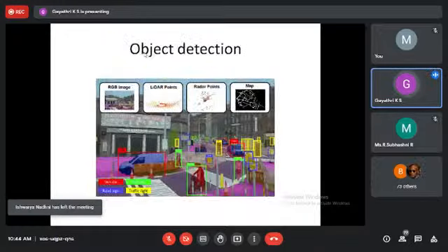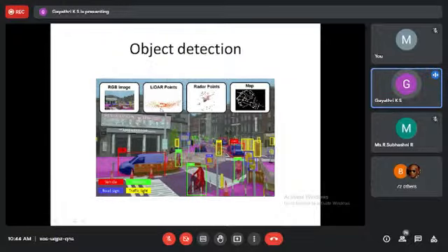So there is a set of algorithms called object detection algorithms in machine learning and deep learning. When you give the inputs of your cameras, your LiDARs, your radar, and the HD map as input to this algorithm, that algorithm will be able to tag. You can see this tagging in the sense of a bounding box. All of you know what a bounding box is. You put a bounding box, and it tells you this is a car. The probability of this being a car is 0.99. The probability that this is a bicycle with a person riding on it is going to be so much percentage.